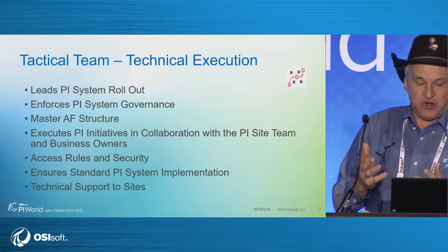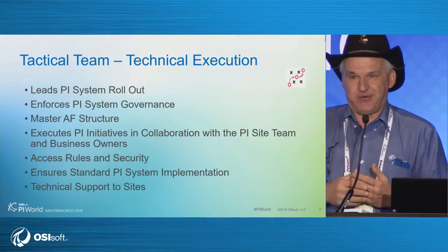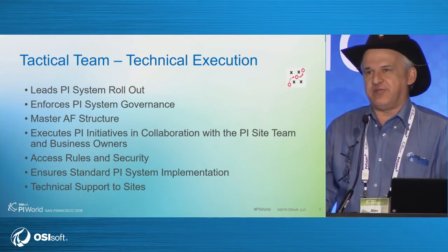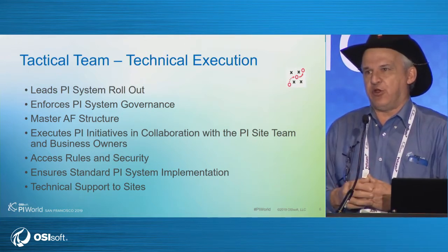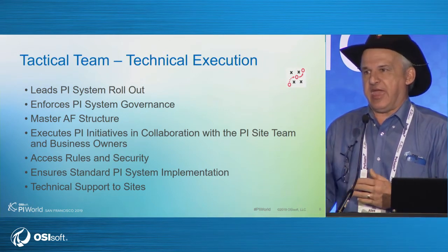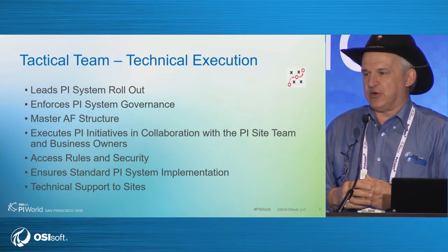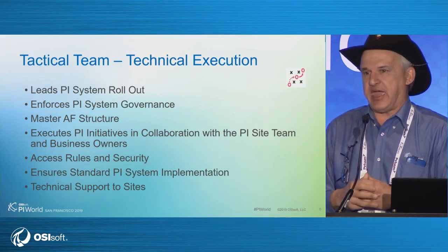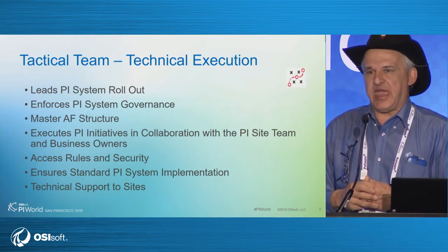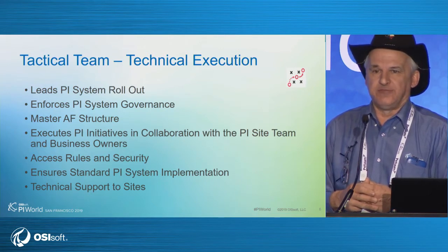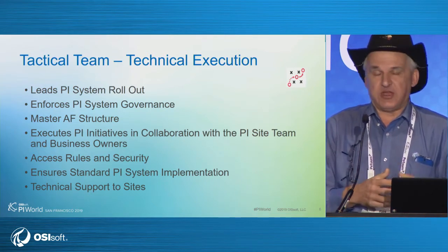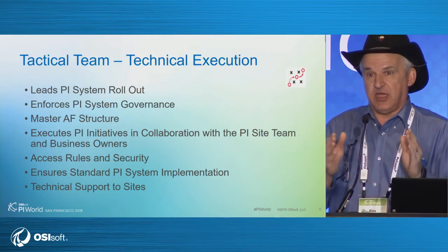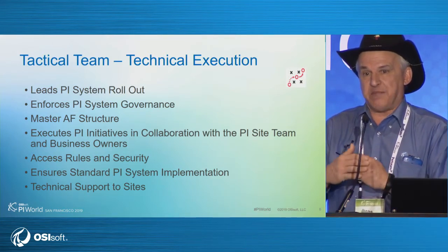The other important part is that you ensure that you keep applying the standards. So some of you, or all of you, have probably had PI for a long time, before AF, and almost all of you will have naming conventions, for example, for tags that use so many standards that you have practically no standard, right? So that's very important here. Then you don't want to get in the same mess. So when I start building the templates and things, you start defining rules and methodologies that I maintain.